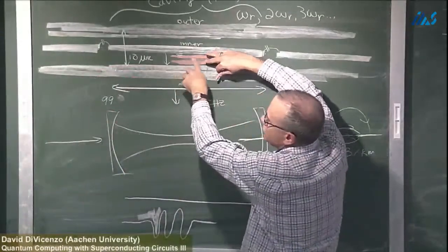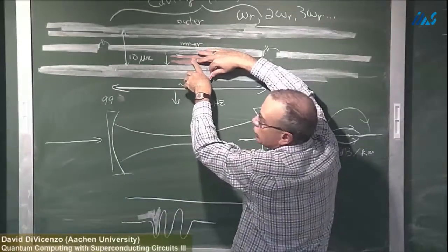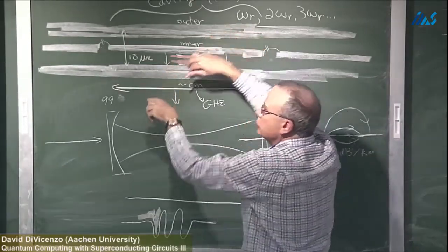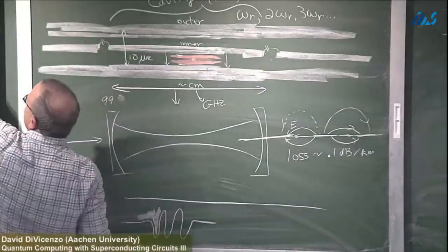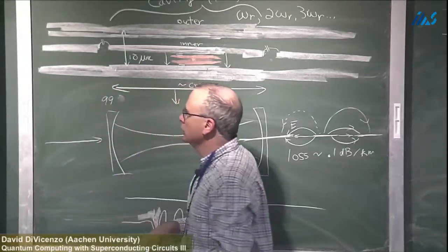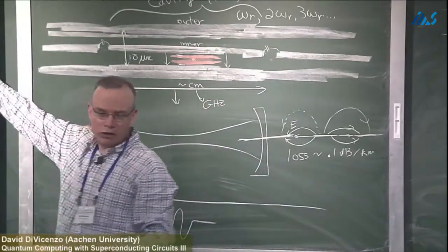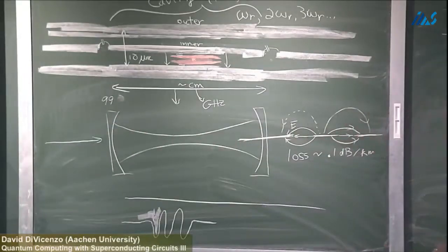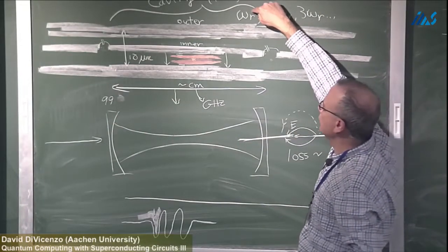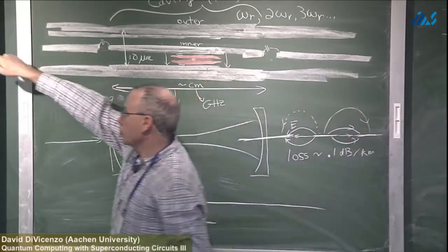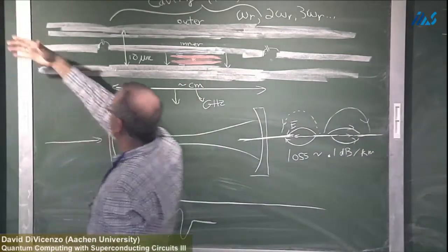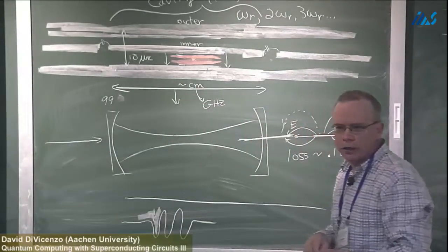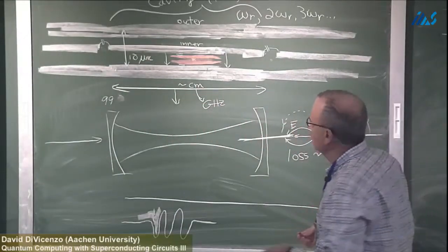So it has a capacitor and a Josephson junction in parallel. And then another capacitor coupling it to the bottom. And then this is the resonator. It's an LC circuit in this model with only one resonant frequency. So I'm only representing by that one of this. And those are, of course, hard to identify. There is not a discrete capacitor and a discrete inductor that I can identify. You can, I'll get to you in a moment.